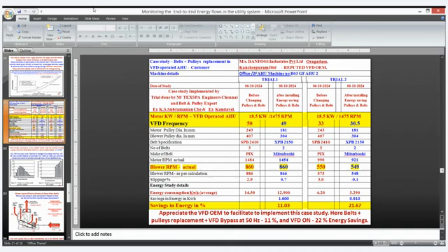For the same given blower RPM of 860 RPM at 50 Hertz, then at 33 Hertz and at 30 Hertz. The energy savings at 50 Hertz is only because of the change of belts and pulleys from V-belts to cogged belts, from 3 belts to 2 belts. This gave a savings of almost 11% at 50 Hertz.